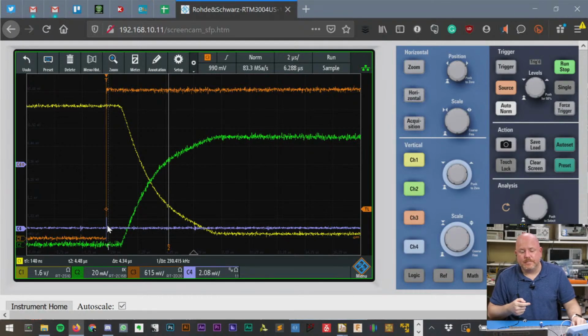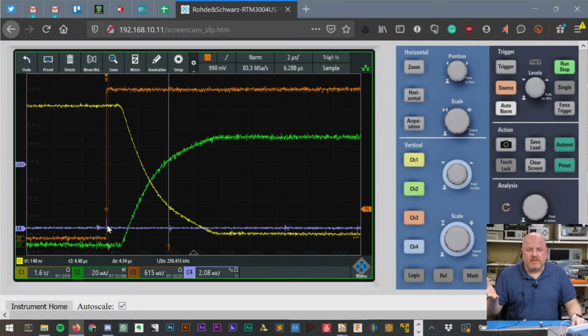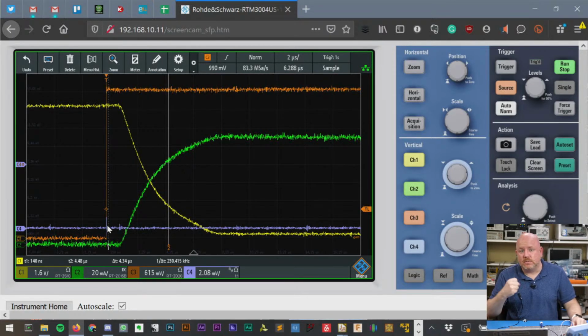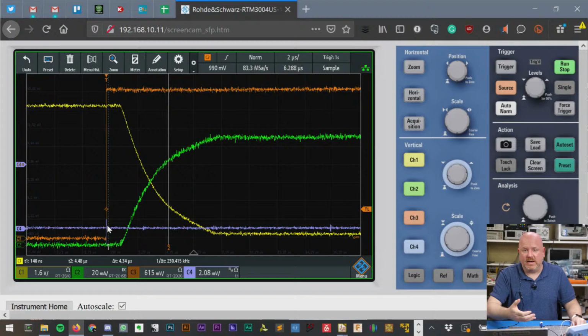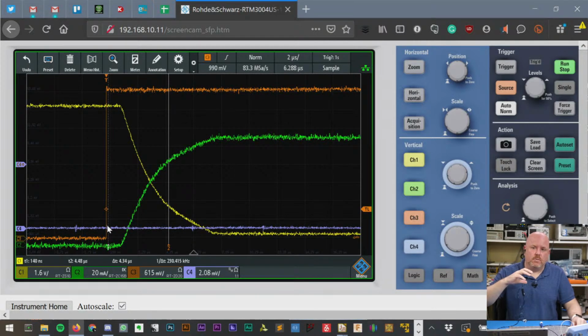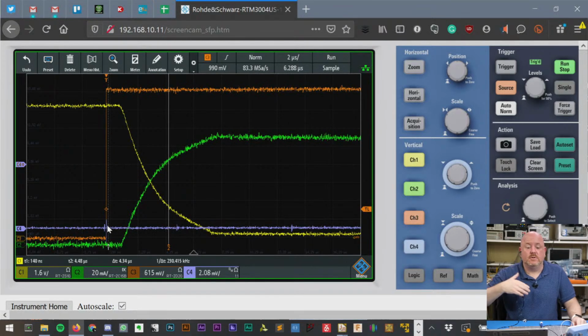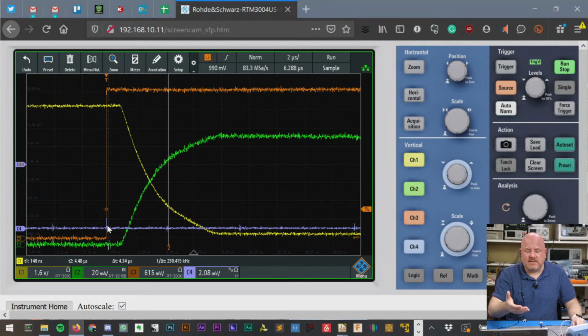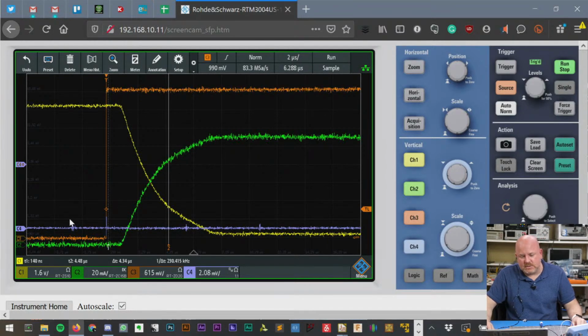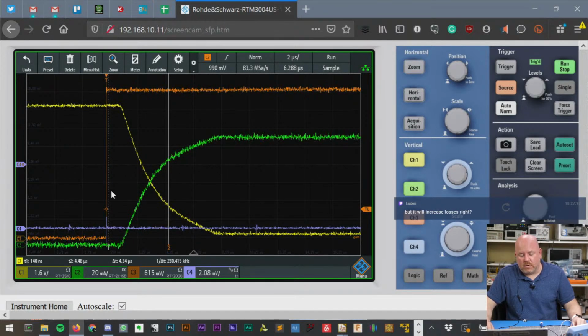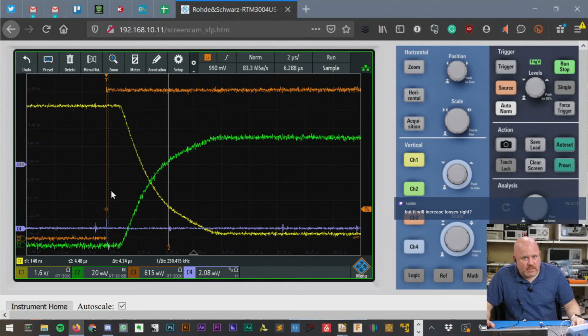Just by slowing down how fast the transistor can turn on, we eliminated the EMI that we were creating from this transistor. One of the reasons we use a gate resistor on the transistor is to fundamentally slow its switching down so that we don't get effects like EMI. Another reason might be that we want to do a soft start, so we don't want shoot through to happen, or we need to delay the time between different stages. There are other reasons, but to me, this is the easiest one to demonstrate: we get much quieter performance. It does come with a trade-off though.